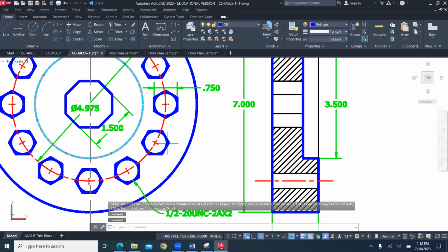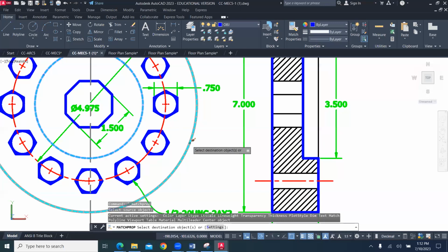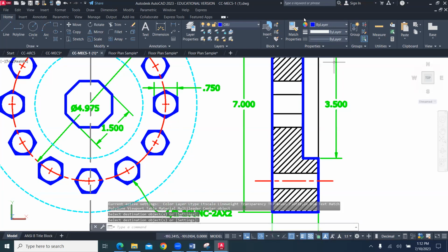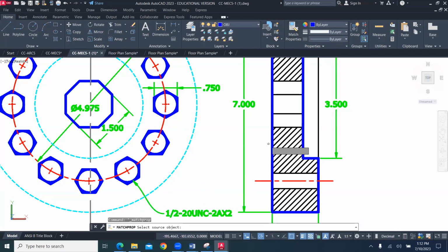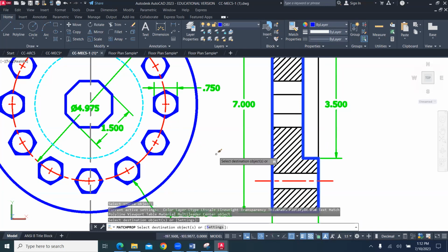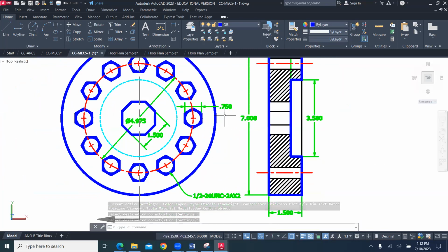the same color and layer as the blue line layer, what we can do is we can go to our match properties command right here, and we could say match the properties. And so if we wanted this to be our source, we could then make this clone it, and it will match those properties. And then vice versa too. We can come back here with match properties, go back to an object line. Match properties is a very powerful command. It works well with setting the properties of color, layers, and line types, also with dimension styles and things like that.